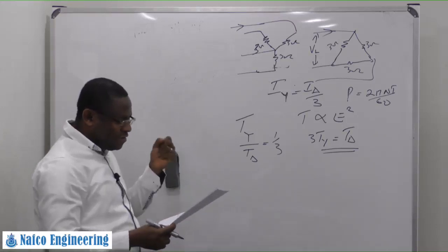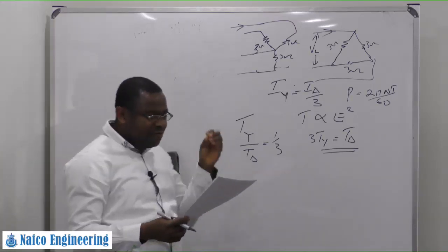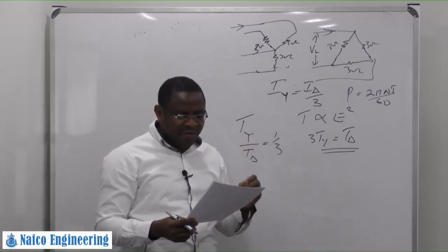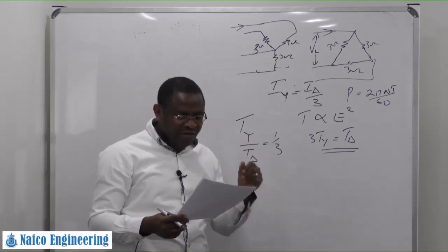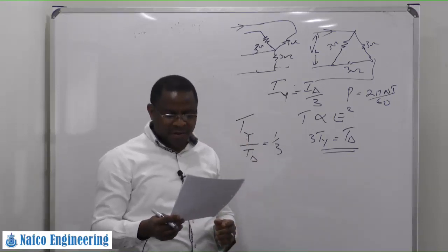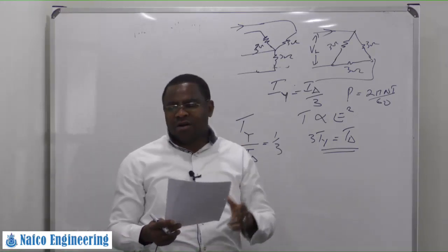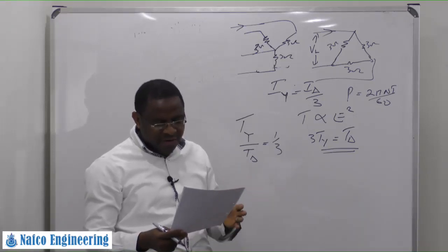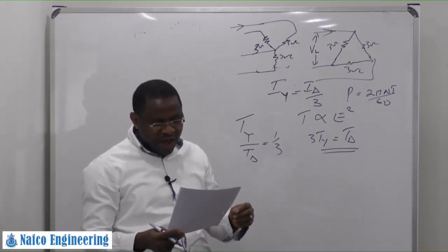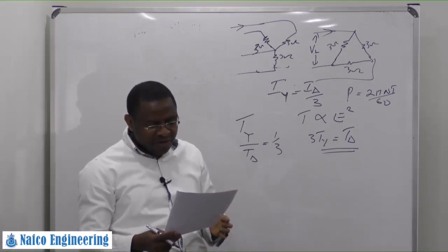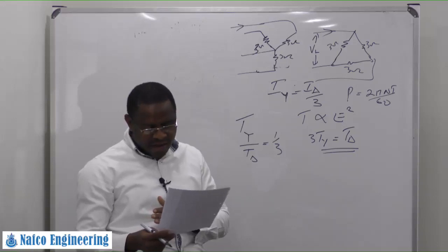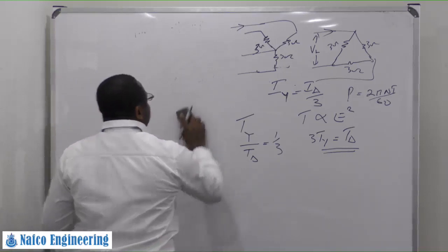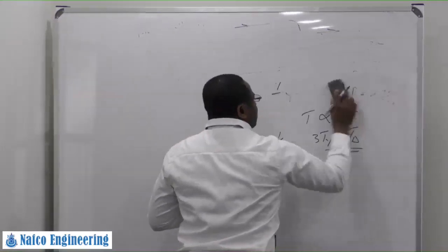Now the motor draws 6 times its full load running current and produces 2.2 times its full load running torque when it is started direct online. Now, it says establish the current drawn and the starting torque when it is started by means of a star delta starter. Okay, let's write the values, all the things that are given to us first